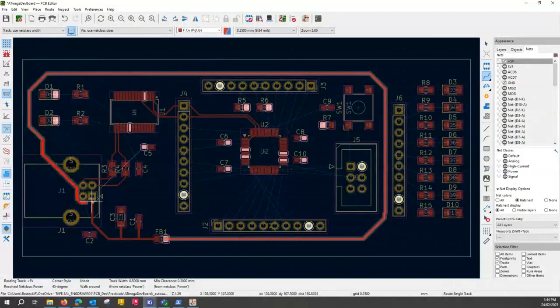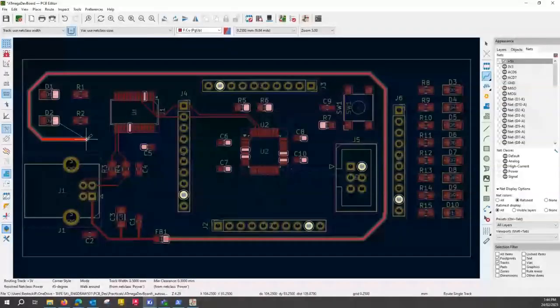And yeah, I could run it back to this one, the main power all around here. But in this case, I'll probably finish it here. You can do a full loop. It's good to have a sort of a power loop, but in this case, I'll do a not fully closed loop. So I'll just run inside of that chip there.